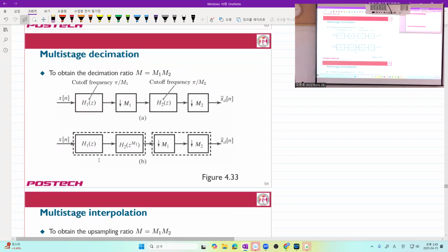Now, instead of using DTFT, we are using Z transform. But you can just understand it as what? Okay, here is an LTI system with impulse response called lowercase h sub L of n. Got it? It's not that difficult. So you have a pre-filter and downsampler, and you have a filter with another downsampler. Got it?